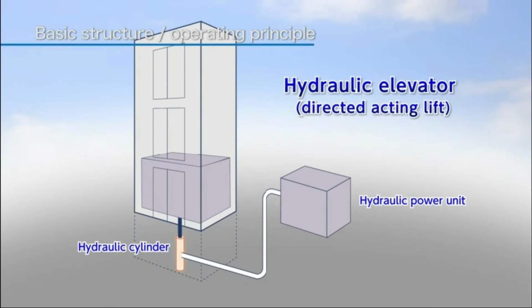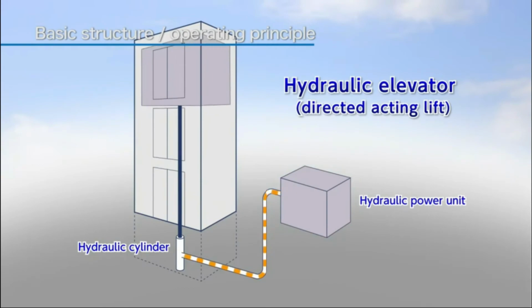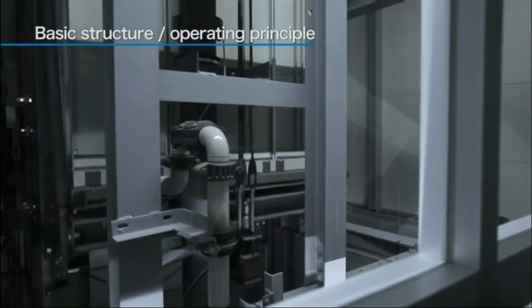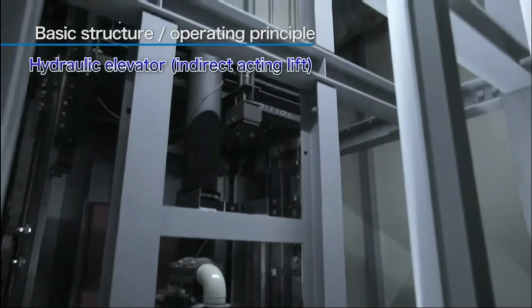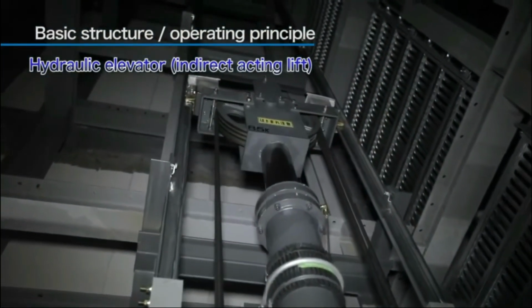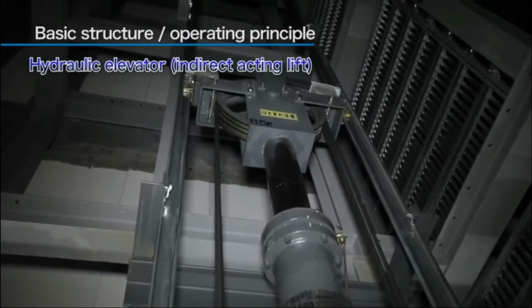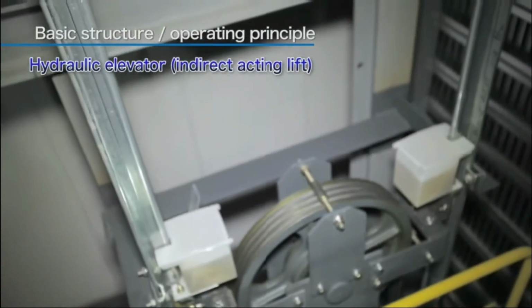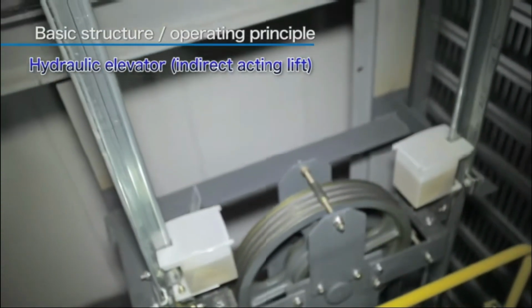There are direct acting lifts, in which the plunger, which expands or contracts under hydraulic pressure, is directly connected to the bottom of the cab, raising and lowering it. And indirect acting lifts, in which the expansion and contraction of the plunger pulls on a rope, causing the cab to rise or lower. The majority of the hydraulic elevators delivered in Japan are indirect acting lifts.